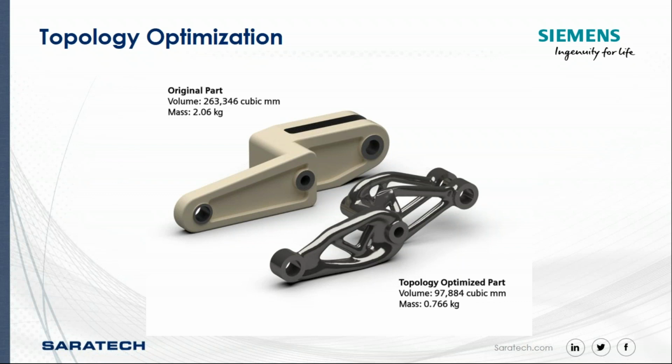So it's a really strong way to design parts, and the reason it's closely associated with additive manufacturing is because depending on the inputs you've given the system, you often end up with parts that would be very hard to manufacture using other methods. So parts like this one would be very hard to machine, for example, using the surfaces we've got here.